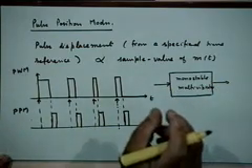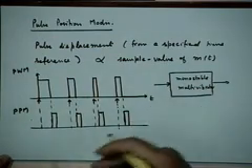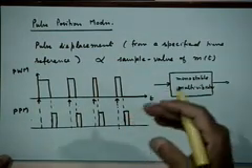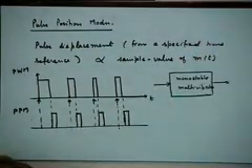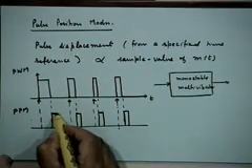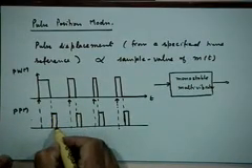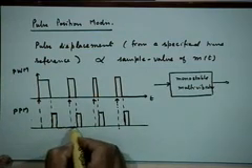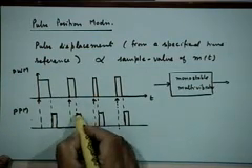It will stay in that state for some time and come back to the stable state. Let's say the unstable state corresponds to a 1 output and the stable state corresponds to a 0 output. So it will temporarily produce a 1 output. After some fixed time, it will come back, which is what you want. You want it to temporarily go to the 1 output, and after some time come back to the stable state, which is a 0 output, and stay there till the next trigger comes.